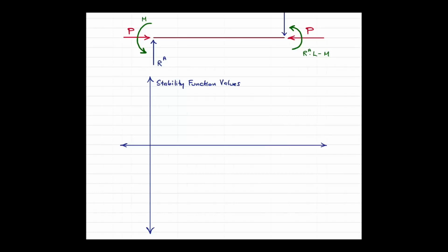The thing is that if you write the stability function in terms of P, and you don't know anything about your cross section, then that doesn't give you any sense, and it could be applicable to just one member. Maybe for this column, P of 1 metric ton is a small value, whereas for that column 1 metric ton could be a very large value.